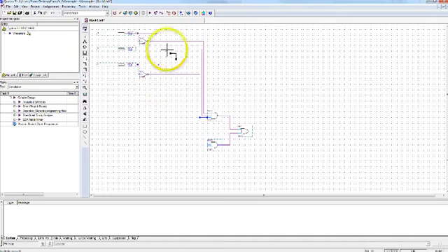Second expression was A, B, C. So I'm going to come down, leave a little bit of space just to differentiate this from the first one. A, B. So I'm going to connect to B, and C. Comes over like that, and over like that. So there we go. So we can see really easily that I've got these three connected to the first AND gate, which is my first min term. These three are connected to the second AND gate, which is my second min term.